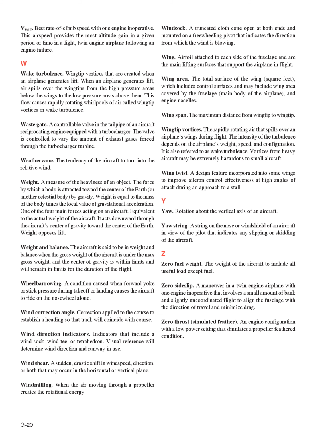Wastegate. A controllable valve in the tailpipe of an aircraft reciprocating engine equipped with a turbocharger. The valve is controlled to vary the amount of exhaust gases forced through the turbocharger turbine. Weather vane. The tendency of the aircraft to turn into the relative wind.